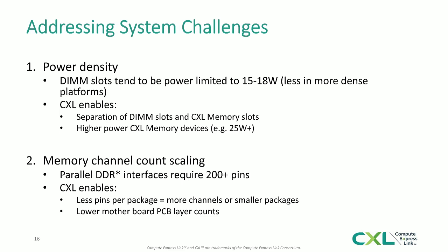So if I look at that more closely, that definitely has PCB layer count implications. For example, just to give you a rough idea, a 6-channel motherboard today is on the order of 12 layers. As you move to 8 channels and up, you're at a 16-layer motherboard, and from there, 10 plus channels are easily over 20 layers, which not only starts to become expensive, it also becomes a rather thick and challenging board to deal with. And that drives things like the back drilling and some of the other PCB technology improvements that have to be implemented that Prakash mentioned at the beginning.